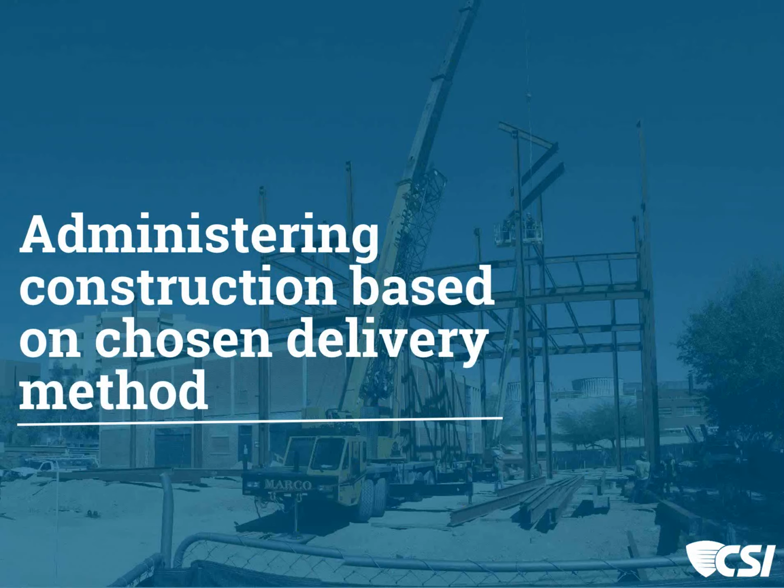Now, mock-ups are very much a part of your construction administration process if they're done after the award of the contract and are used as a measure against what you will measure the project. So when you have a mock-up done for brickwork and windows and flashing and waterproofing, it is in your general requirements defined that it is a part of the expectation or a part of the quality control on the project.